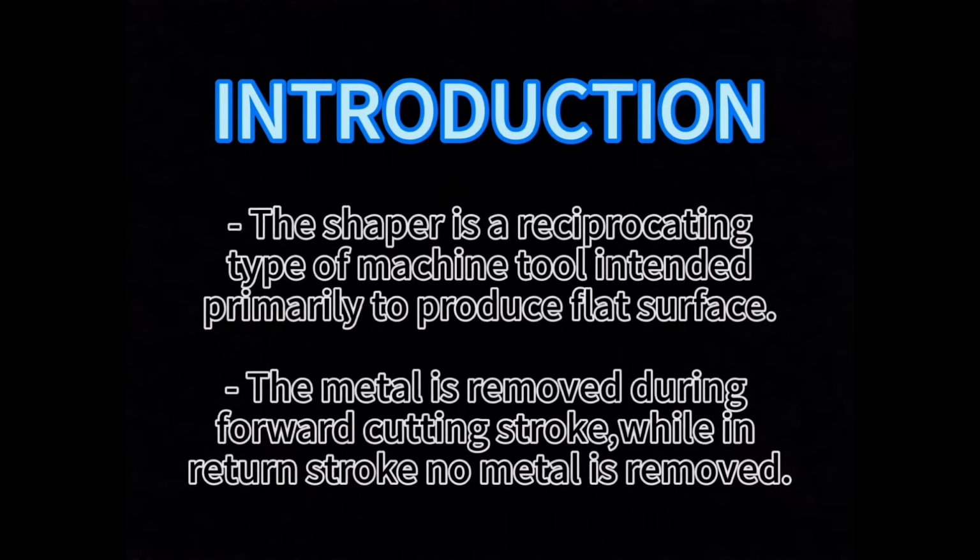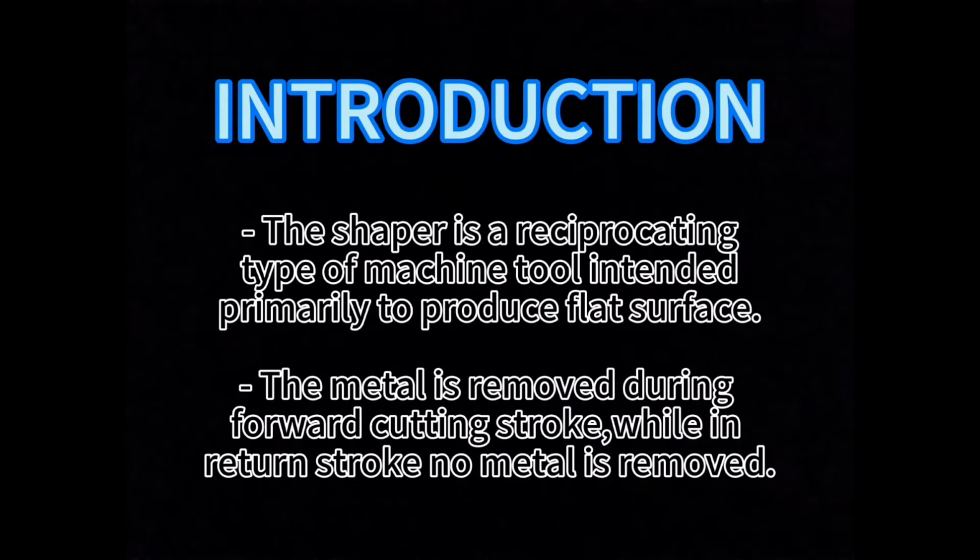The shaper is a reciprocating type of machine tool intended primarily to produce flat surfaces. In a shaper machine, the rotary motion of the drive is converted into reciprocating motion of a ram holding the tool by means of a mechanism inside the column of the machine. In a shaper, the metal is removed during the forward cutting stroke, while in the return stroke no metal is removed. Therefore, in order to reduce total machining time, the shaper mechanism should be designed.